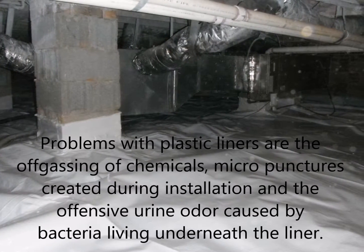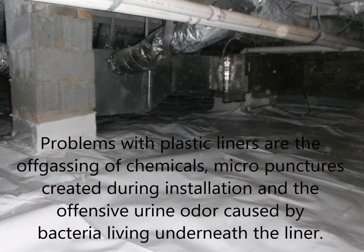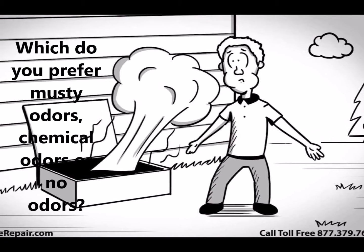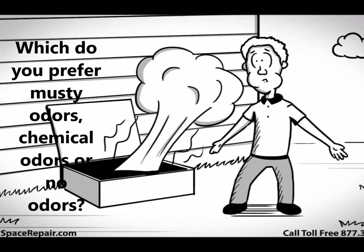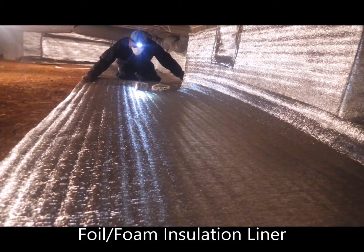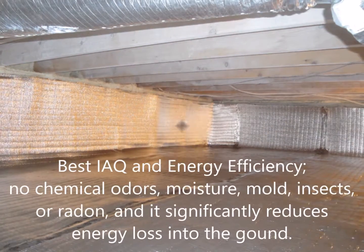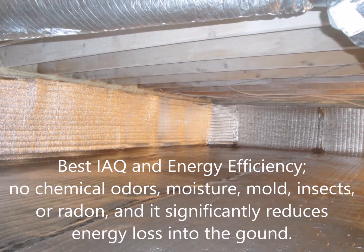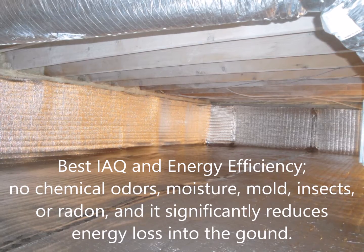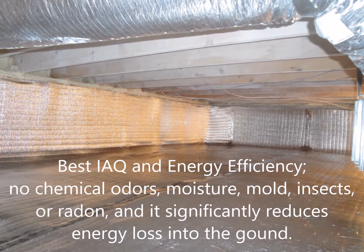A problem with plastic liners are the off-gassing of chemicals, micro-punctures created during installation, and the offensive urine odor caused by bacteria living underneath the liner. So which do you prefer, musty odors or chemical odors? Here at Indoor Environmental Systems, we prefer to use a foil foam insulation liner which covers the ground and the walls. This is the best for indoor air quality and energy efficiency, since there are no chemical odors, moisture, mold, insects, or radon, and it significantly reduces energy loss into the ground.